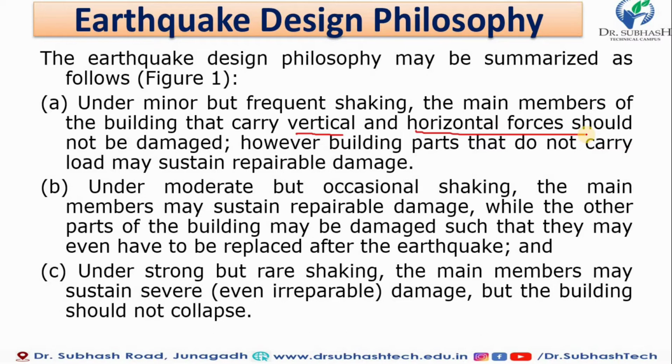The main member may sustain repairable damage while the other parts of the building may be damaged such that they may even have to be replaced after the earthquake. So we have allowed it in moderate shaking. But our main part should be repairable, and the minor parts, or you can say the rest of the building, are replaced